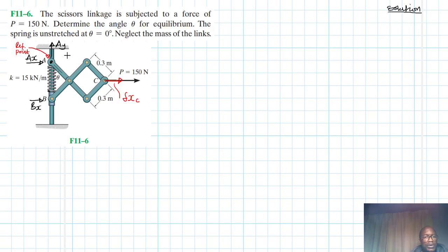Once we do that, we need to draw a deformed configuration due to this virtual displacement, which is imaginary. Imagine applying a very, very small virtual displacement in the direction of that particular force, and point B is free to move in the vertical direction. So draw a deformed configuration.